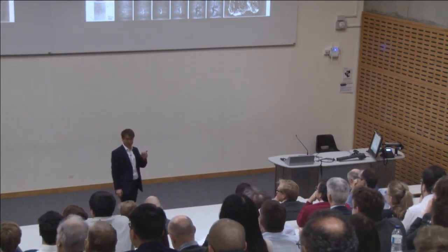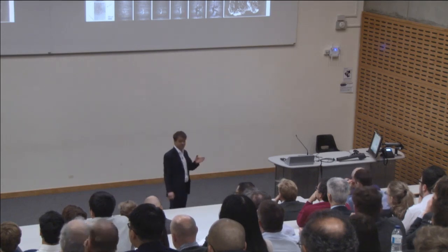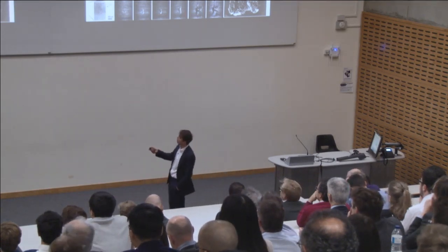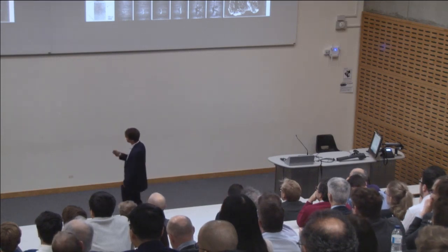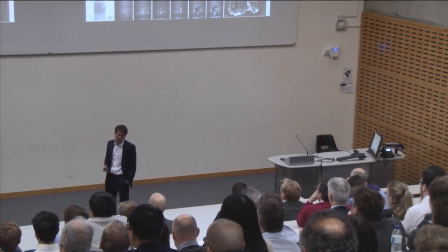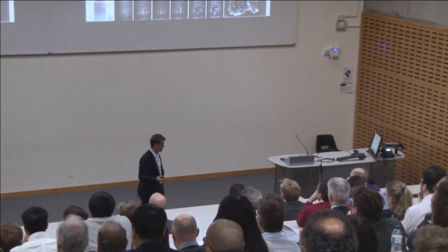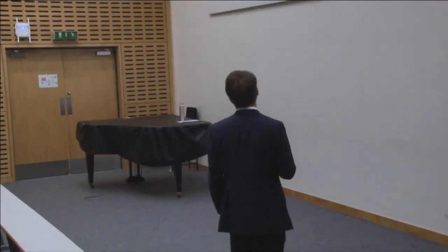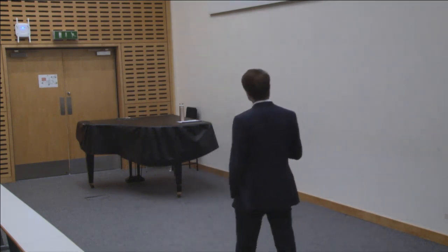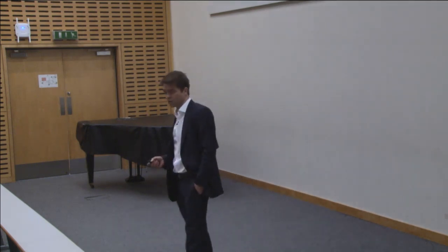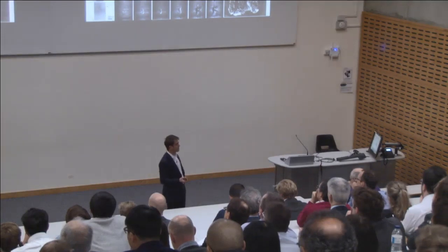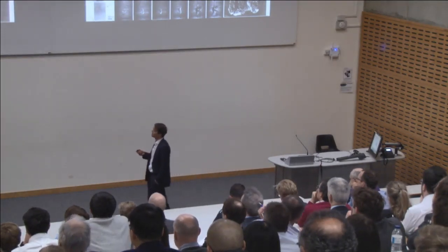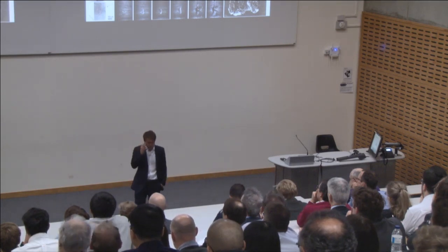First, you have some damage accumulation period, which eventually results in initiation of a crack. And then that crack propagates, in this case across the surface, it can be subsurface, and creates a pit on the surface. Once you've created that pit, the damage propagates very fast until the component has failed. Traditionally, it's this crack initiation phase that's been considered as the life dominant, and propagation phase has been assumed to be negligible in length. As I say, surface and subsurface initiated.